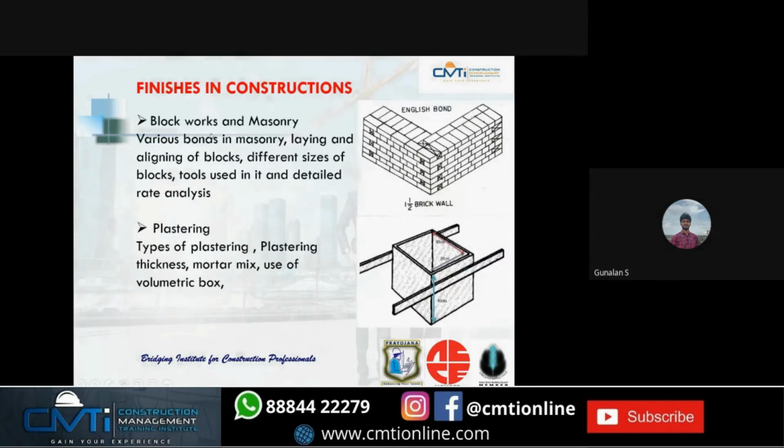Finishes in construction: block works and machinery. This is the main part. Generally in today's scenario, everywhere they use only English bond, but there are other bonds like header bond and stretcher bond. Generally they use English bond nowadays. Laying of block is an important aspect, and the laying should be done exactly. Here also you use the 3-4-5 method for exact laying and alignment of the block masonry.